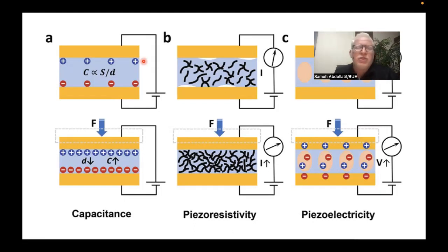As we already discussed in the previous two lectures, usually we have to use what we can call an interfacing circuit for our sensors. The job description for this interfacing circuit is simply to process the signal detected by the sensor into a suitable signal that can then be processed by other stages. For example, we usually give the example of the ADC, or analog digital converter. Say I have a piezocapacitive material, which means that whenever there is a force, this force will be converted into a capacitance. That's great. But what we need for an ADC is a voltage variation from 0 to some VCC or whatever. So we need to convert this variation in capacitance into a variation in voltage that is compatible with the next stage, for example the ADC. So this is the job description for the interfacing circuit in this case.